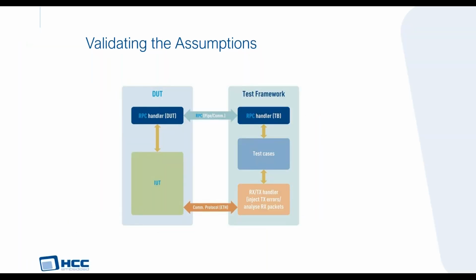Once we have that integration into the target, one of the things that's really important to us is to be able to verify that when that is integrated, having made some modifications, maybe not having made any modifications, but maybe using a different compiler, a different CPU, a different endianness, different RTOS, things change. If things change, we need to make sure it's still behaving consistently with how it did before.